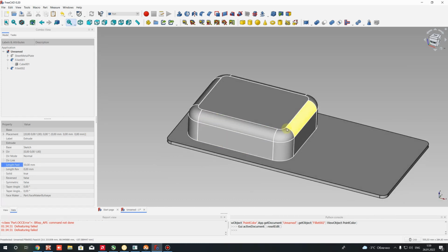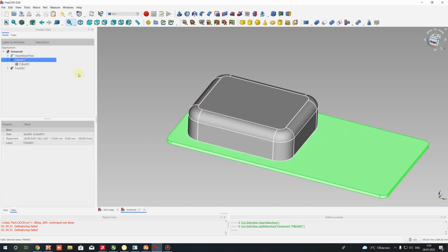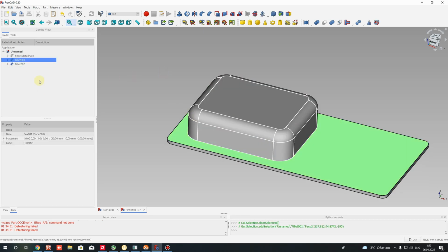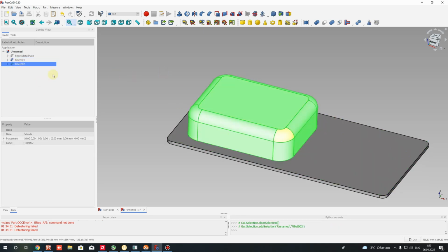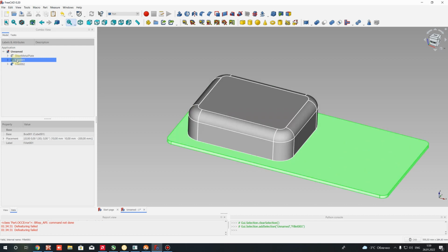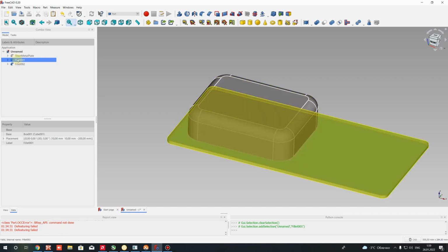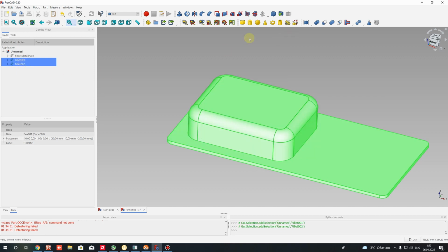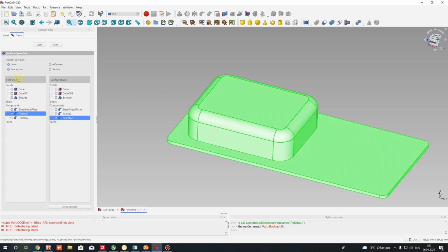After that we have these two different bodies here. We have this flat plate and this part in different bodies. We have to merge them. Press the Ctrl button for Fillet001 and this part, and for both let's make a boolean operation to merge them into one part.